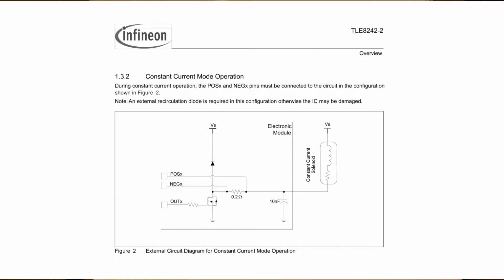The example just given may seem confusing until it is remembered that the IC controlling the solenoid is a low side driver, meaning that the opposite end of the solenoid is connected to a steady 12-volt supply, like the vehicle battery in automotive installations. Thus, when the voltage applied to the drive side of the solenoid shows as 12 volts on the scope, the voltage across the solenoid is 0 or off. When the voltage on the driven side of the solenoid is near ground, about 12 volts appears across the solenoid, turning it on.